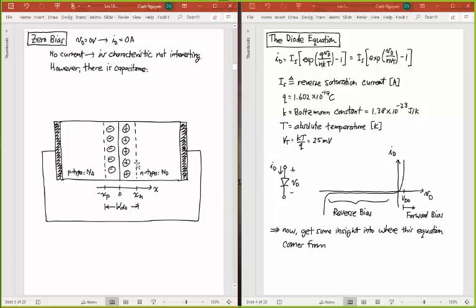However, what is interesting is what happens physically within the diode structure. Okay, and so what happens physically is that actually you do get capacitance here. And you get capacitance because remember what a capacitor is. A capacitor is basically charge on two plates that's controlled by a voltage. Well, if I look at this, I've got some charge here, positive charge. I've got some negative charge here. And so I am basically separating charge when I create this thing.